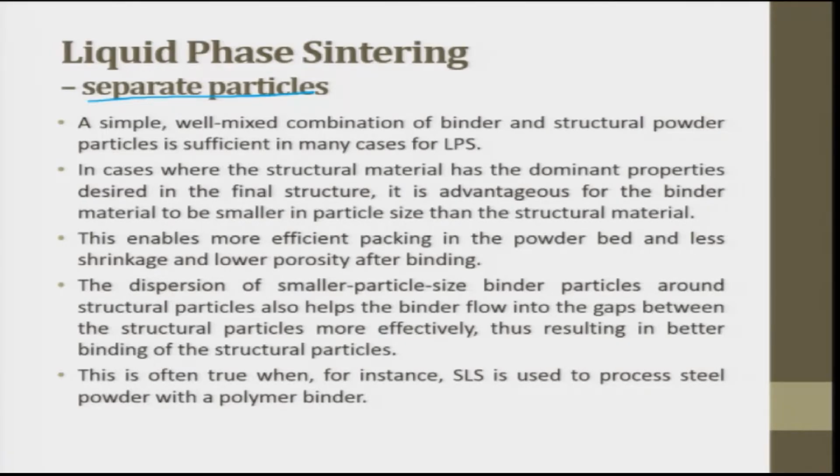So the shrinkage is very low, and the porosity after binding is lower because wherever there is a pore, it will get filled up. The dispersion of the smaller binder particles around the structural particle also helps the binder flow into the gaps between the structural particles more efficiently, resulting in better binding of the structural parts.